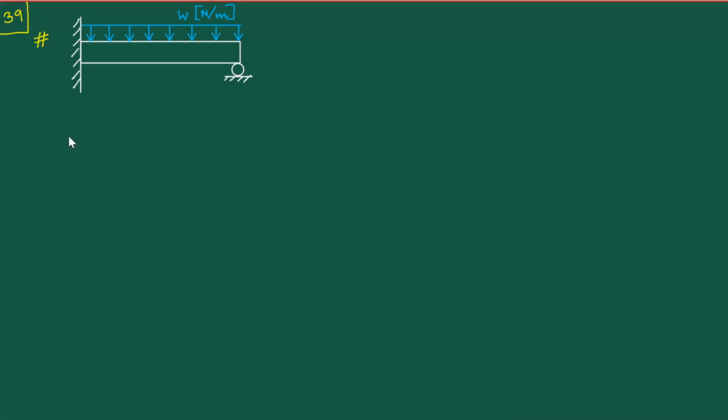Hello everyone. We'll continue our discussion of problems in this lecture also. So the first problem we are going to address here is with this physical setup, and you note that this problem was just like a cantilever beam as we'd been discussing previously, but we have now made this problem statically indeterminate, and it now becomes a different sort of problem because of the presence of this roller support here. Okay, this is very much a statically indeterminate problem.